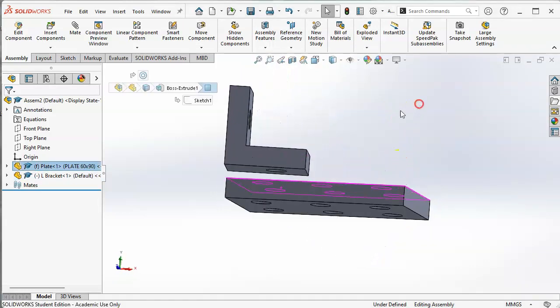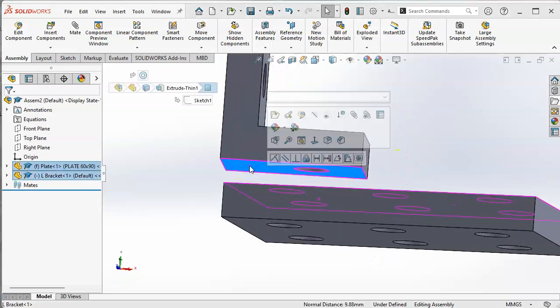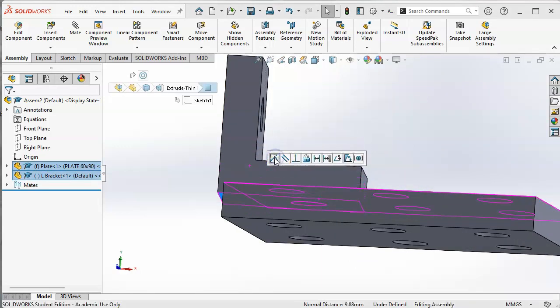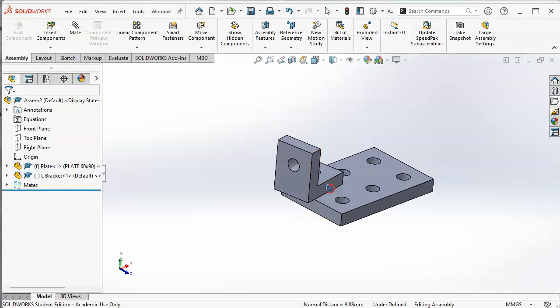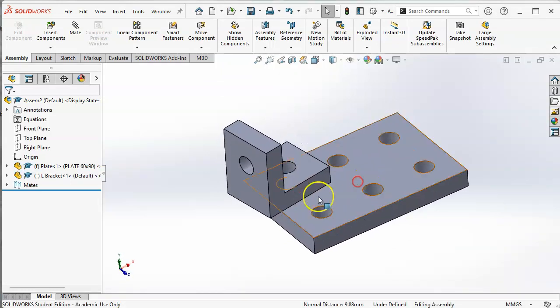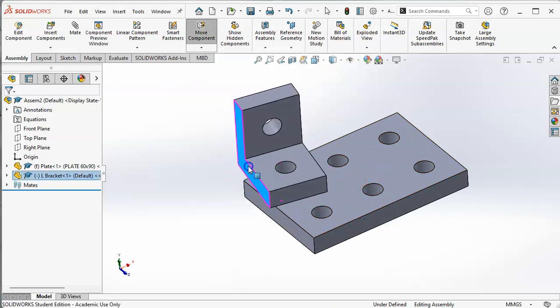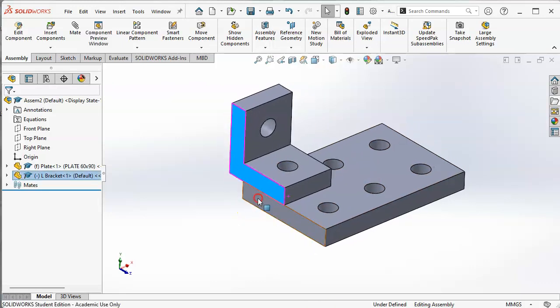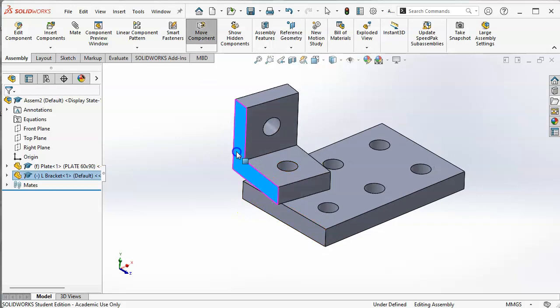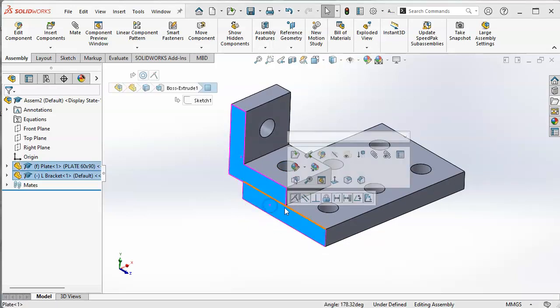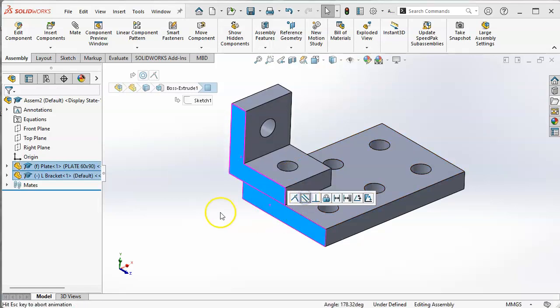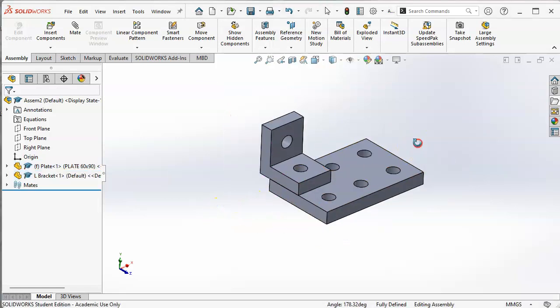We'll click and hold down the control and select and go coincident. And then again, as I hold down the middle mouse wheel and rotate the view and then left click on the part, I can rotate the part and then select control select. I'm probably going to go parallel there again.